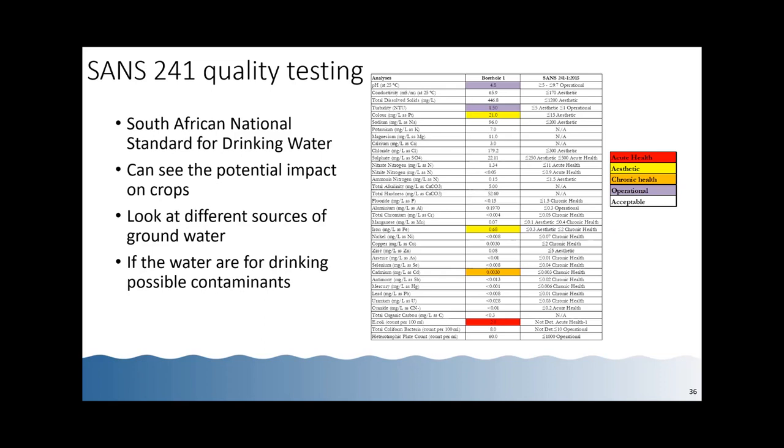So if the water doesn't taste nice and isn't pleasing either in smell or in taste, there's some limits for what those parameters should be in the water. And then it goes all the way up to chronic health, where if we supply water that has, for instance, cadmium or uranium or cyanide in it above a certain limit, and for an extended period of time, we can start causing some serious health issues to the people that are